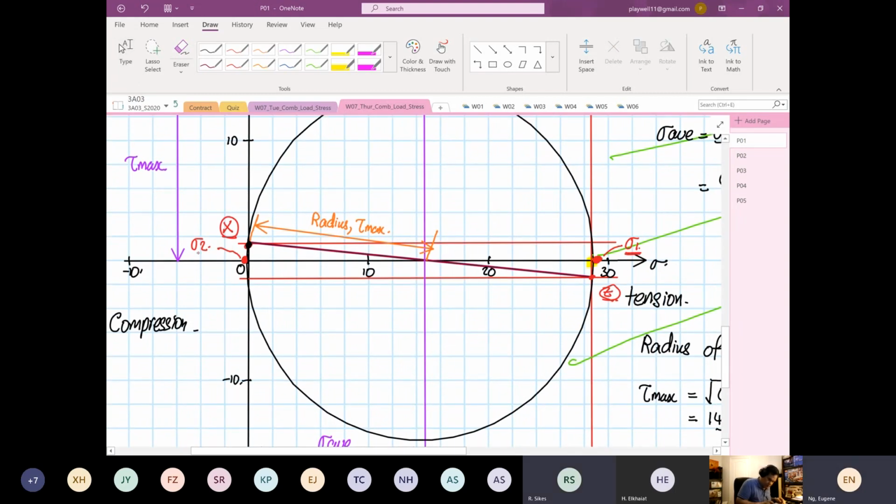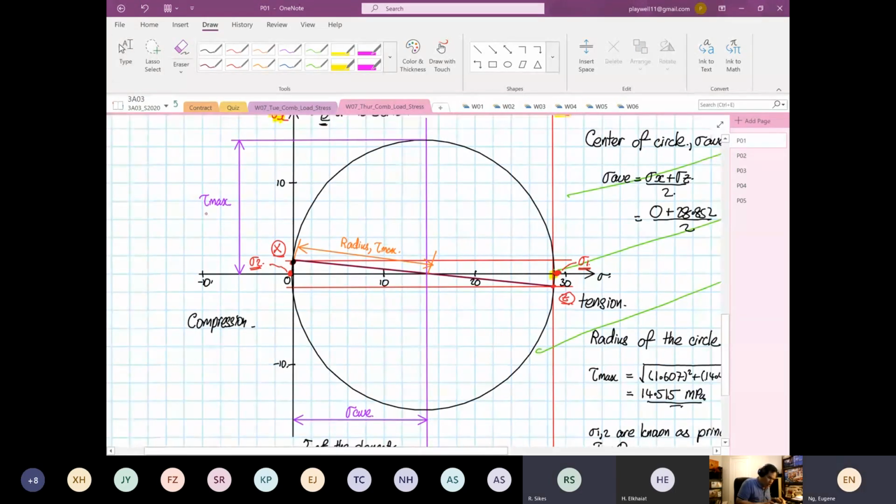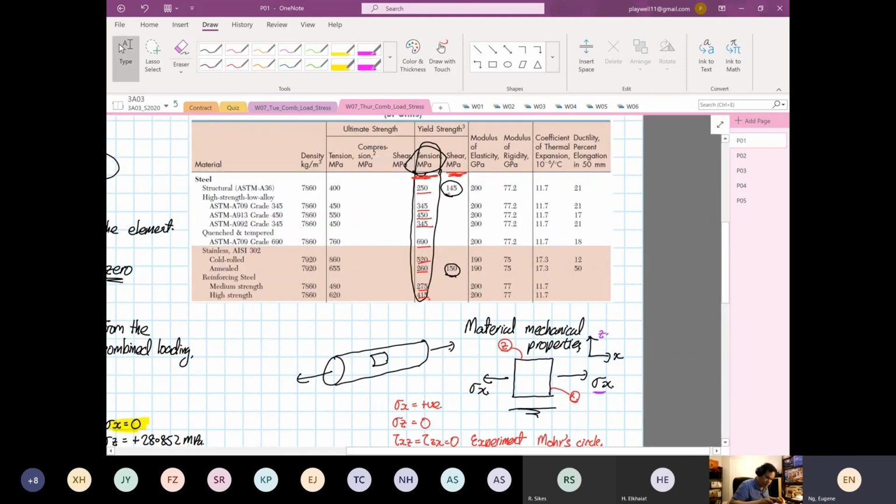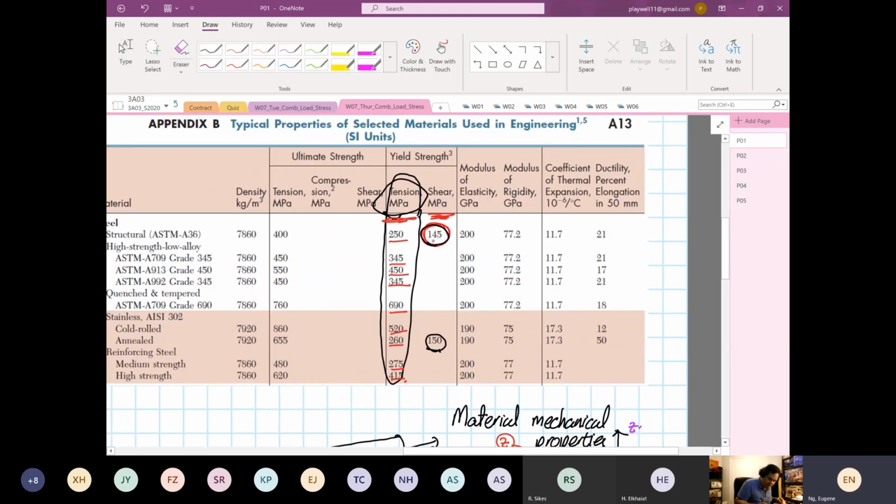Is there a label for the maximum shear? No, we just call it maximum shear. Okay, thanks. That's not our principal stress. We just call it the maximum shearing stress, right? So when we look at maximum shearing stress, when we look at a handbook like this, we have to make sure that it's below the allowable yield in terms of shear. If not, your material will fail in shear. Okay, and this is dangerous territory. What you see is the shear is less than what? In tension.